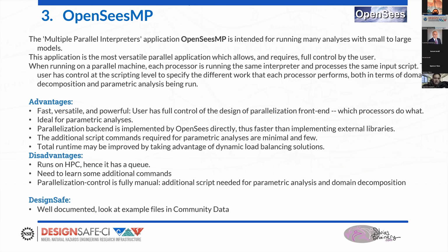If we switch over to OpenSeesMP, which is the multiple parallel interpreters, now you get a lot of fun, let's call it that. It's the most versatile because it allows you, but therefore requires full control by the user. Each processor interprets the same script. It's all done in one script.